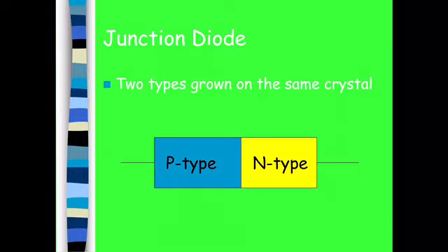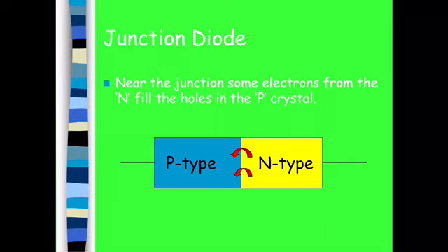You see, because close to where the P and the N type meet, there's too many electrons on one side and too many holes on the other. So some of the electrons naturally jump over and fill those holes. This leaking of electrons from one type into the next across the barrier is probably why we have modern society. It's the creation of this thing, which is essentially a switch which will work at light speed, which is the junction diode. Before this we had valves, enormous things that look like light bulbs that were really almost virtually useless.